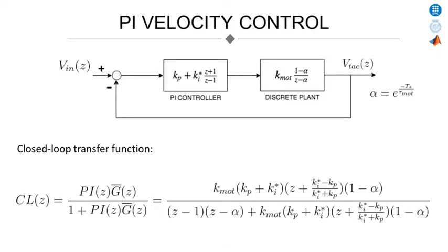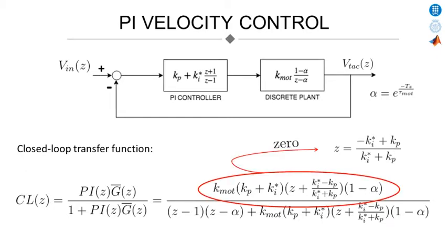As we saw on practice 3, the obtained closed-loop transfer function of the PI velocity control had 2 poles and a 0. By means of the controller's parameters we were able to place the poles and design the stability and the temporal response of the system. But placing the poles by the controller's parameters in this architecture has a drawback. As we can see, the 0 is also automatically placed when placing the poles, so we obtained an undesired overshoot, as can be seen in the following figure.